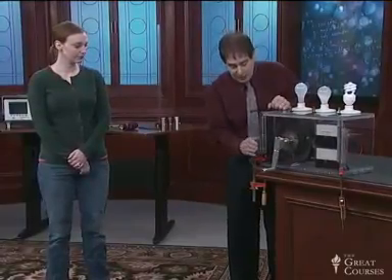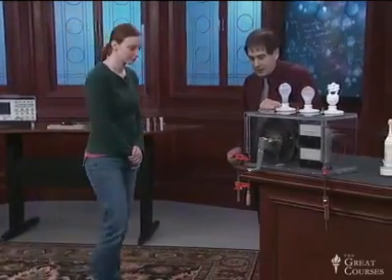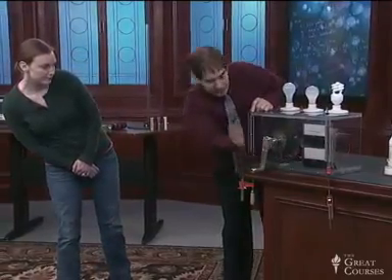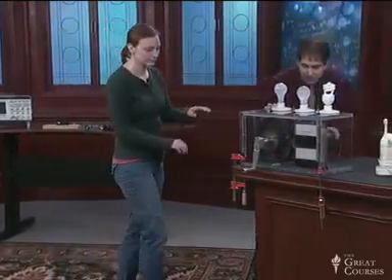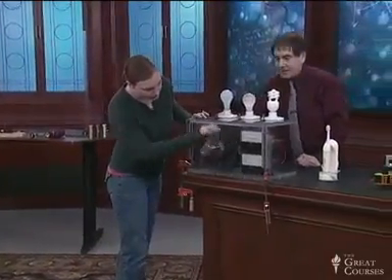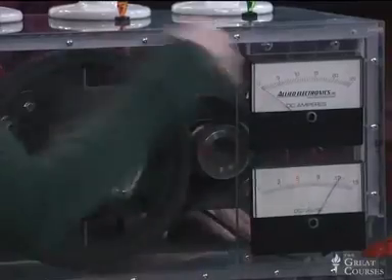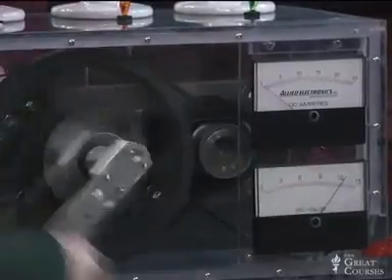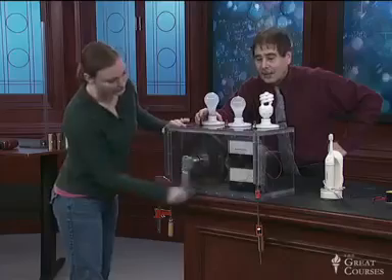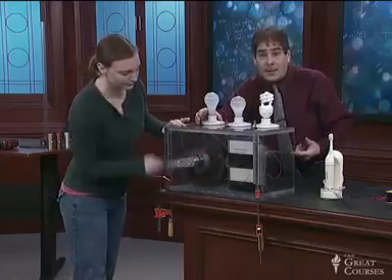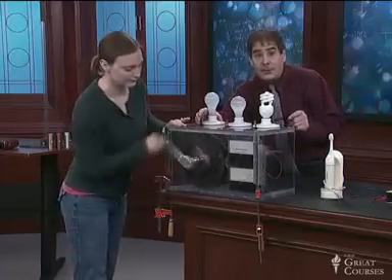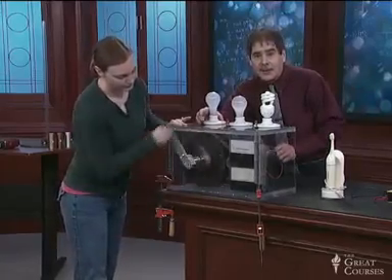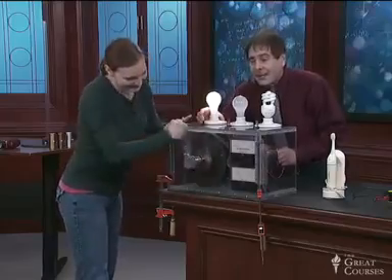So I would like Laura to start turning that crank, and crank it at a nice pace. And Laura, if you can, crank it so that voltmeter reads about 12. It's not crucial, but get it up about 2/3 of the way. So crank it nice and fast. Okay, pretty easy. So she's having no trouble cranking that generator. There she goes. Real easy. Just keep it going, just like that. Nice and easy. She's spinning coils of wire in a magnetic field. But right now there's no current through those coils because I'm not asking them to supply power to any load. Keep going, Laura.